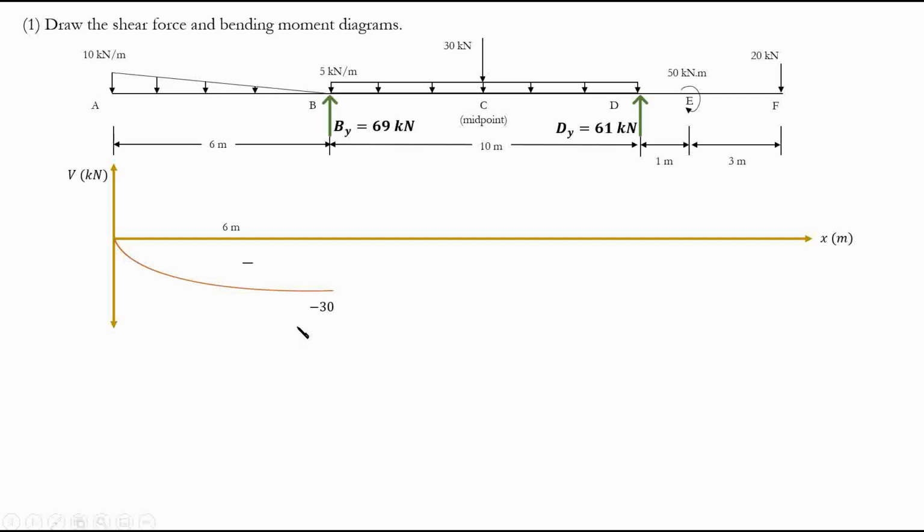Of course, I'm not going to mention negative or positive slopes, just to avoid confusion. Obviously, this is negative. The force is going down, right? So this is a negative slope here. But we're only going to consider intensities and the magnitudes. So you see, it is intense here, and then the intensity goes down, which means that you will have a large slope here, and then after this, you're going to deal with a flatter slope. And at the end, at point B, what is the slope? Just to the left, it's 0, right? So here, in the loading diagram, your intensity is 0, which means that the slope for the shear diagram is 0, right? Simple as that. So that's how we draw our shear force diagram from point A to B.